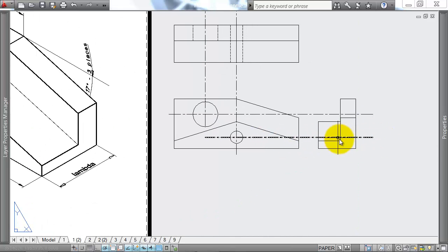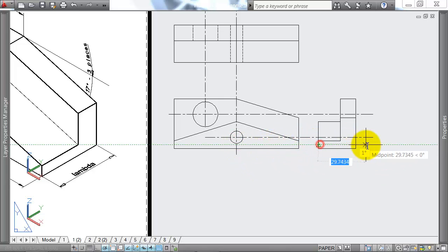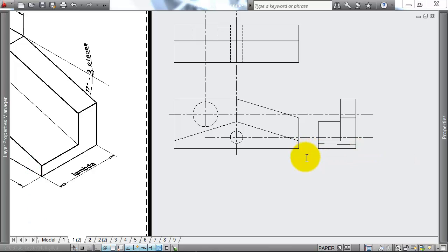What else do I need? So now I just need hidden lines on this view, and this drawing is done. So again, the bottom circle, whoops, it's not a very neat line. The bottom circle has hidden lines which go from the very front to the very end of the shape. And this top circle has hidden lines which only exist in the back part of the shape.